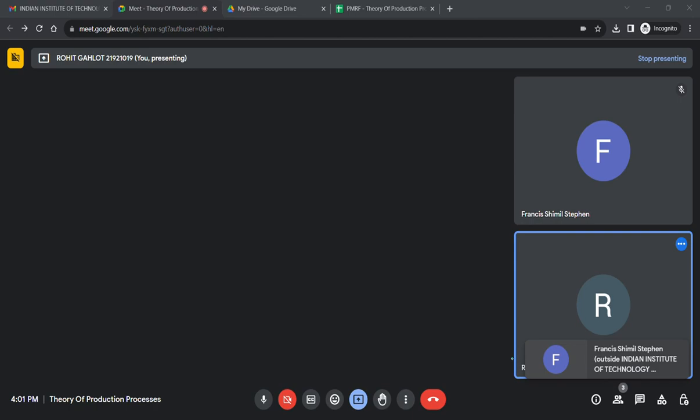Generally they are half or equal, if they are side or top riser. But the main thing which I wanted to cover in this tutorial was, firstly, we should always remember that our V by A of the riser should be greater than or equal to V by A of the casting. So this is the major learning